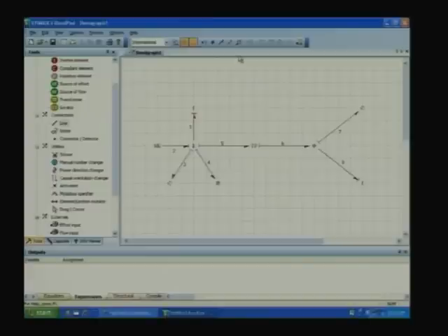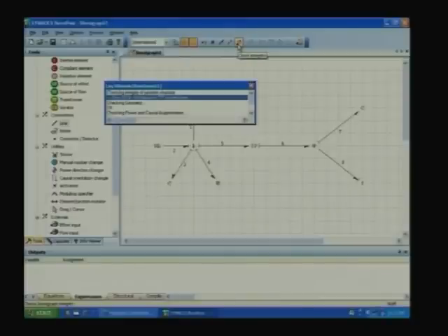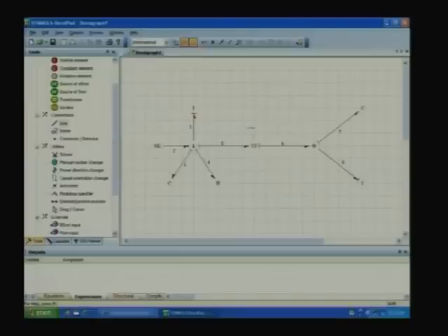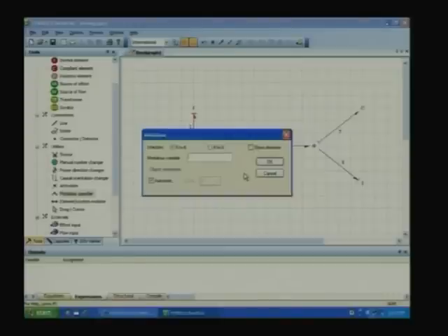Okay. Now, you need to check whether it is correct or not. That means, the consistency has to be checked, for which there is an icon here, check integrity. I click it, it checks. It says that modulus for transformer is not declared. Obviously, it has to be declared, otherwise it does not know what it is. So, here is an icon called modulus specifier. So, I go on the transformer and click it.